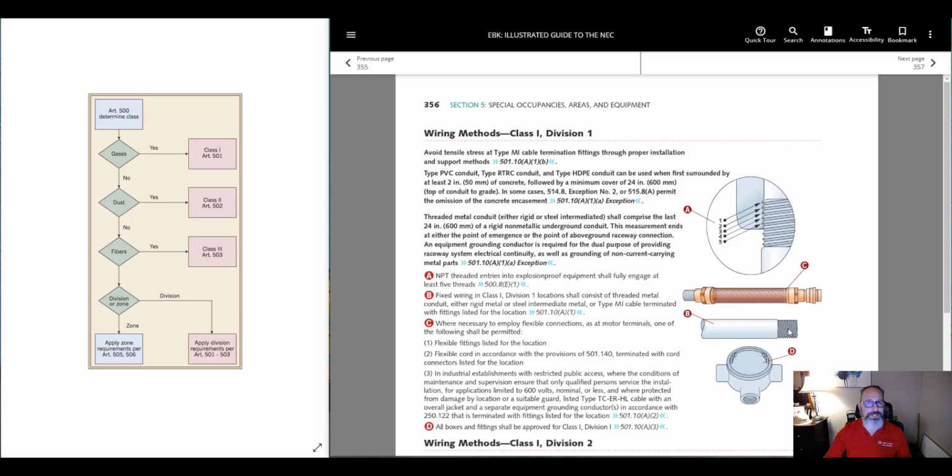If you do what I just said, and I've never had a problem with OCal doing it, you need to treat the threads before you put it all together so that it's protected from corrosion. It could be down in a saltwater area where it's a salty environment and you want to protect the pipe. OCal or plastic coated rigid is what's normally required for underground when installing around explosion proof environments.